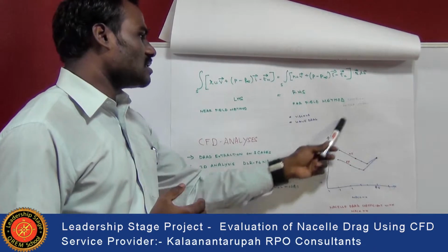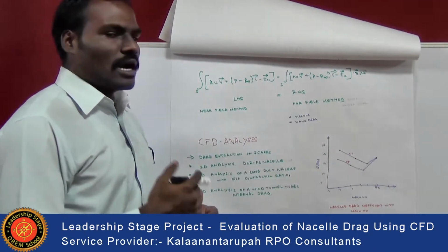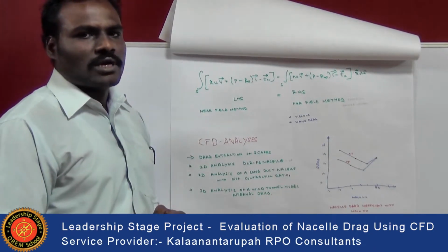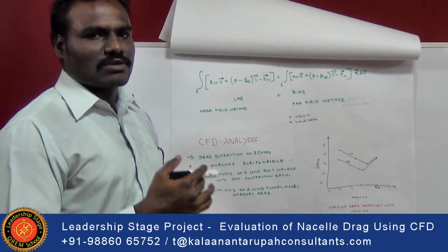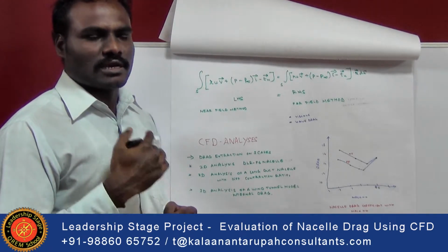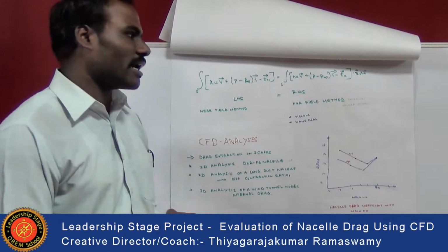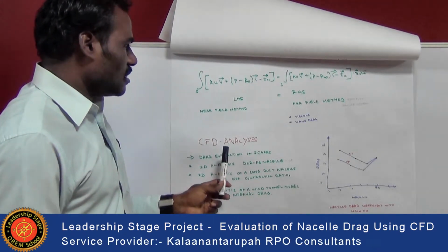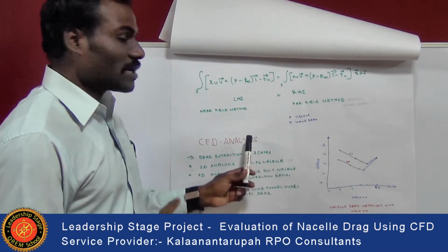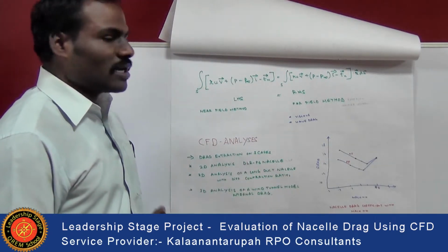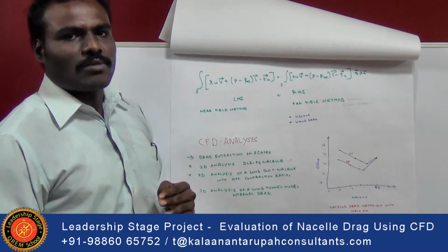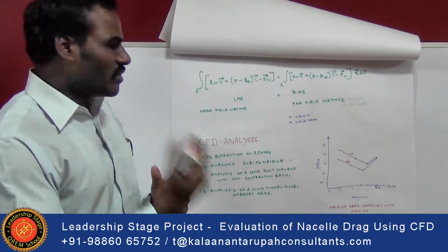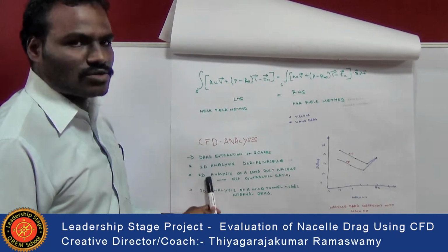Now we are going to discuss the far field method and how it helps us in finding out the drag of the nacelle, and how it affects the performance of an aircraft. Here the analysis is carried out with respect to the internal as well as the external part of the nacelle. First the analysis is carried out using CFD.